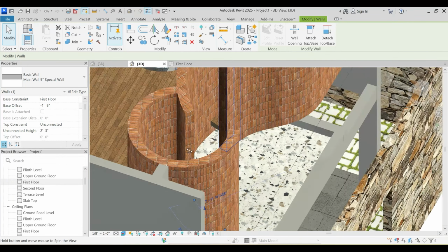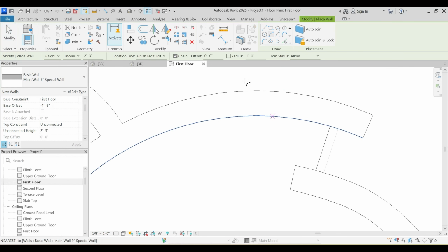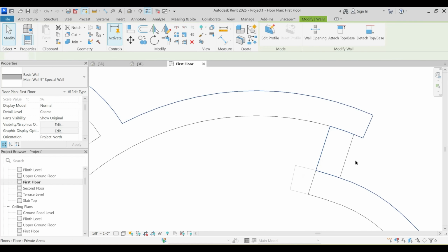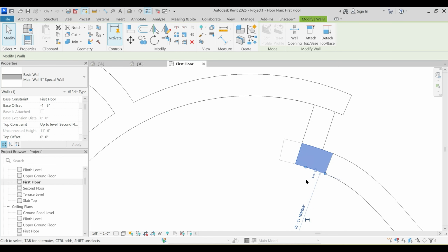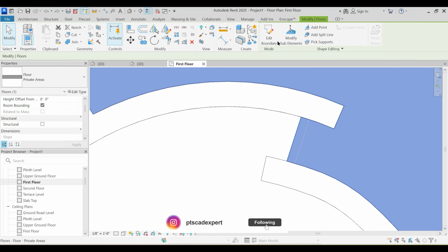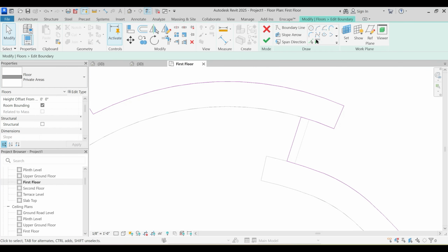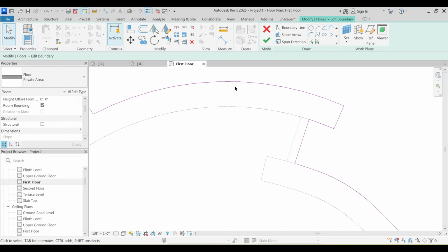The same thing here also there would be. So just say CS and pick lines, select this and just flip the direction. Join conditions with Revit are very weird. Edit boundary and first set pick line, TR, and join this to this, and join this to this, and delete.